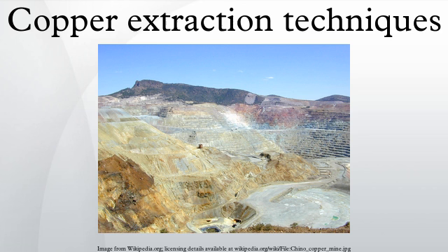Roasting. The roasting process is generally undertaken in combination with reverberatory furnaces. In the roaster, the copper concentrate is partially oxidized to produce calcine and sulfur dioxide gas. The stoichiometry of the reaction which occurs is 2 FeS2 + 3 O2 → 2 FeO + 2 S + 2 SO2. Roasting generally leaves more sulfur in the calcine product than a sinter plant leaves in the sintered product.